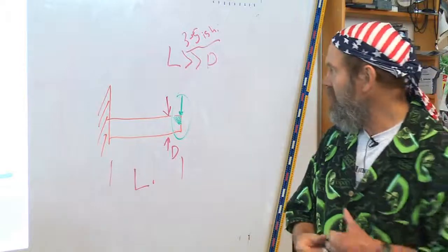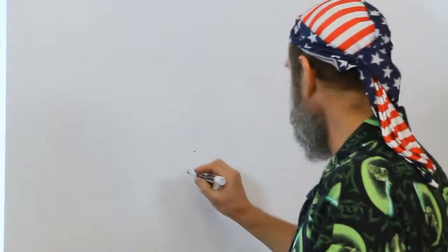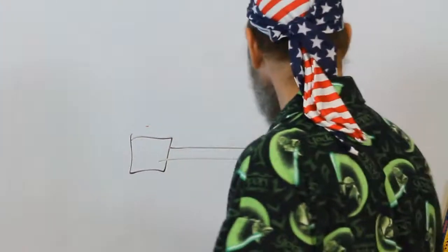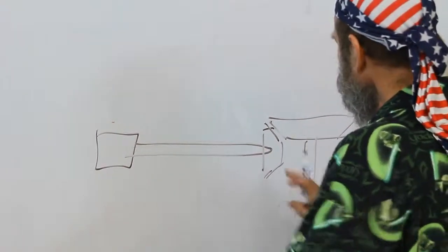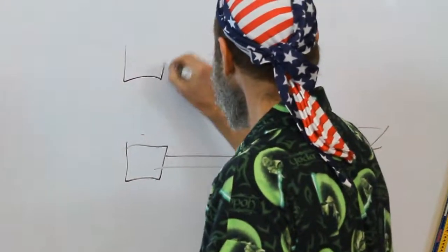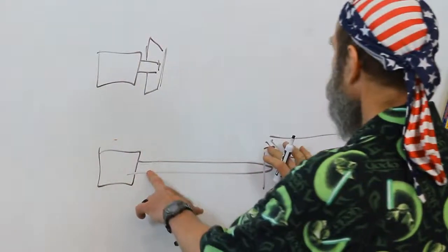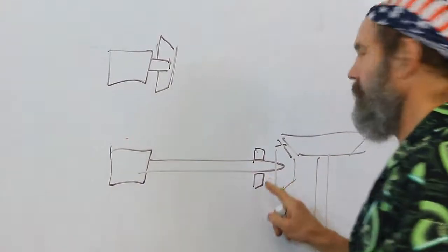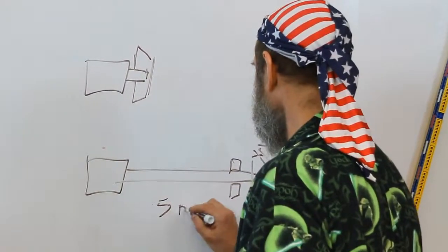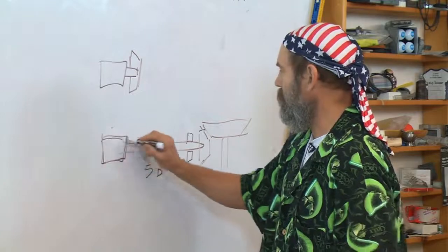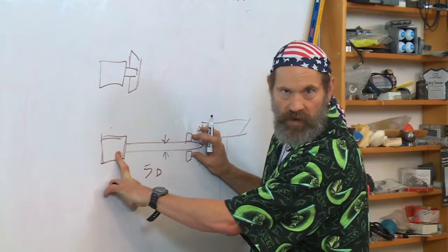So for example, remember that drawing I did earlier, that sketch on top of the picture where we showed here was a motor and had this long shaft extension to the gear and another gear. You either want this gear to be right up tight, if you're using the shaft of the motor, or way far away and then you put a bearing here, an outrigger bearing it's called. That way, if this bearing is at least 5 of these diameters away from the motor, it will not overconstrain or control this motor's bearings, and it won't wear them out.